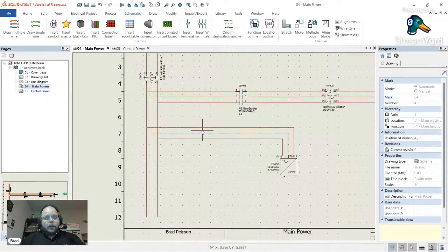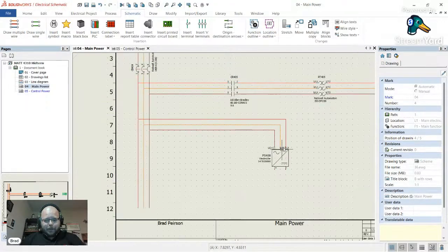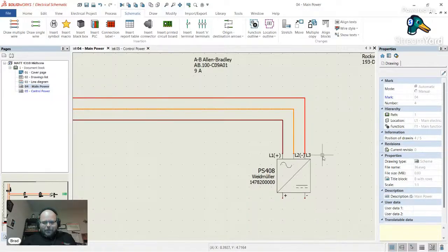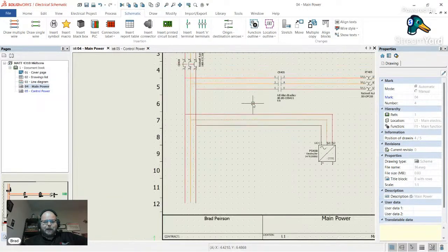One thing we need to do that I always do is we need to protect this. Always protect the incoming on the power supply. Now, again, I'm not nuts about a three-phase 24-volt power supply. In my experience, they fail frequently, they fail early, and they fail often. Worse, when they fail, they tend to fail at a frequency that I can hear.